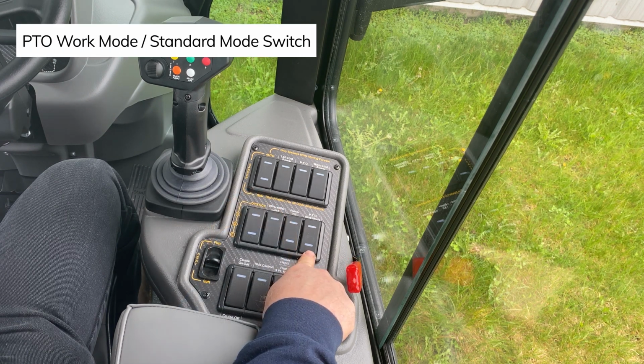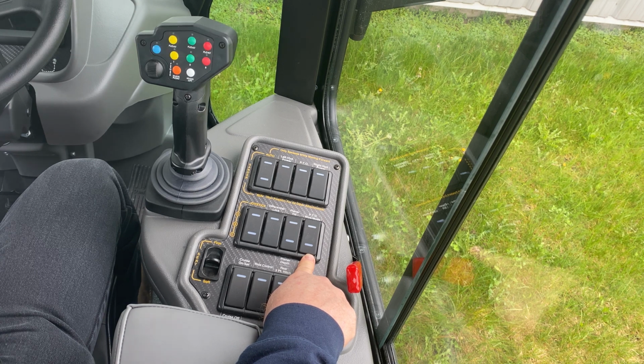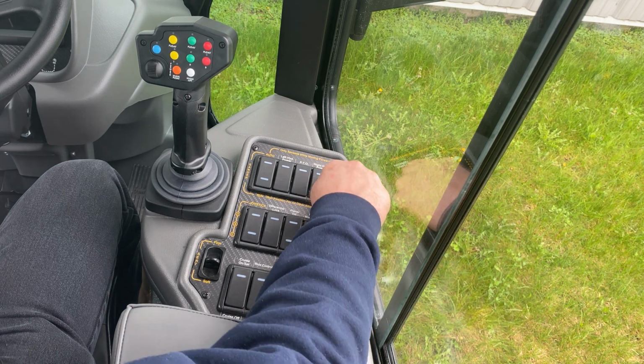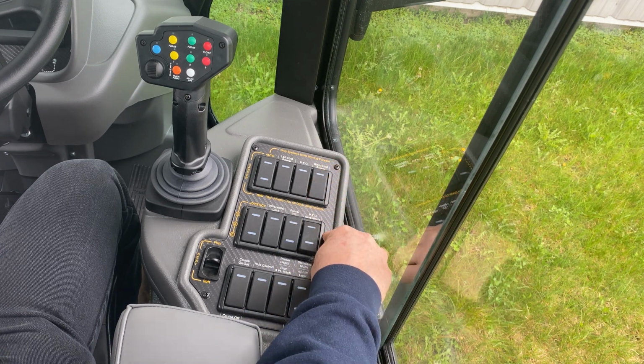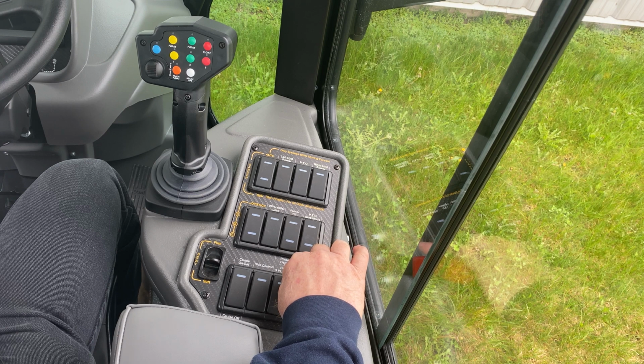PTO work mode standard mode switch. This switch allows the operator to control engine RPMs automatically or manually. When PTO mode is selected, engine RPM is controlled by the throttle lever to the right. When standard mode is selected, engine RPM is now controlled by the foot pedal on the right side of the floor.